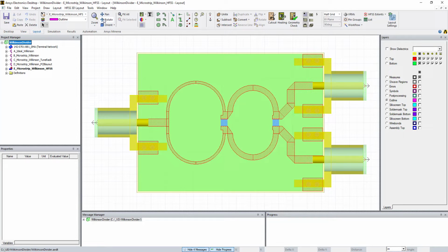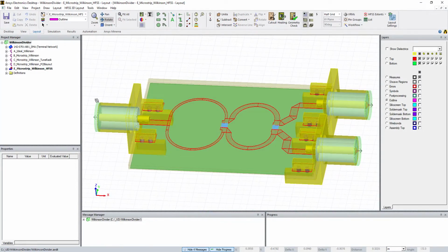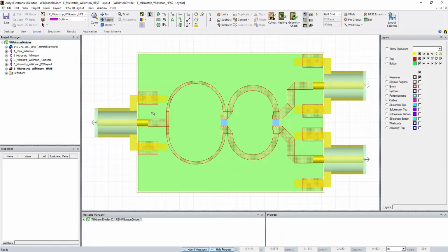Essentially this is what we're going to design, a multi-stage Wilkinson power divider. If you look at the top, you come in here and it separates into two. These are called radial bends. You make these two radial bends for your stage one, or actually going from right to left will be stage one. So this is your first R1 and then Z1. This is R2 and Z2 relative to the paper. If you use the nomenclature of the paper, they call this R1 and then Z1 and then R2, Z2. But you're still using these radial stubs.